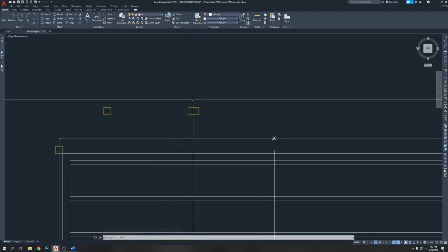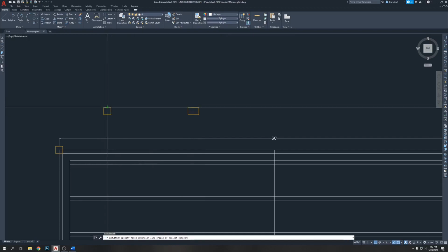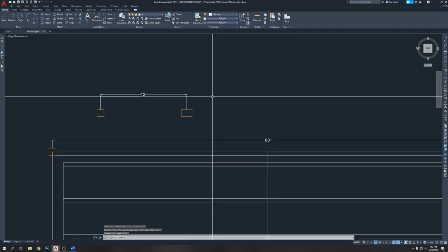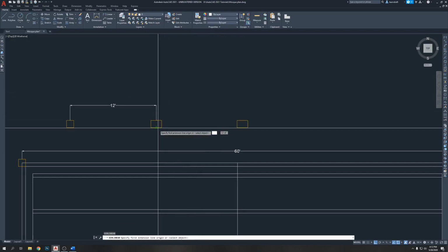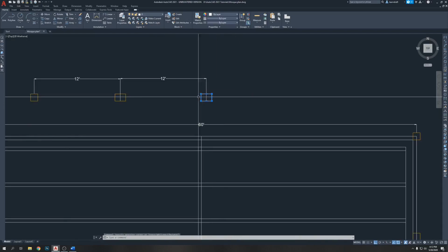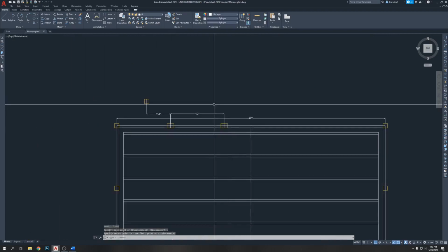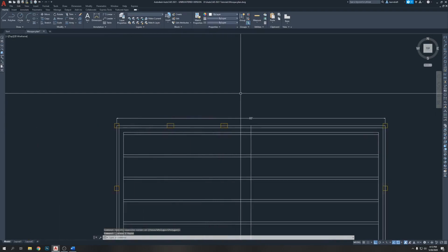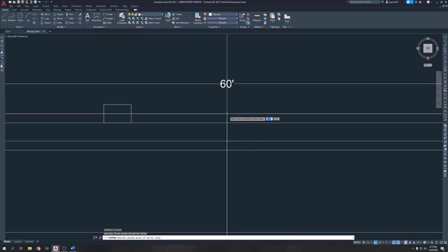Okay, so I'm going to click this one, check center to center, which is 12 feet. Now we need to copy this one 12 feet. Hopefully the 18-inch moved along. Good. Now we're going to bring this with M, enter, select this outline so you can place it on this outline, and it's set. Let's delete these things to clear, and then we're going to mirror this with MI, enter, center line, click, enter.